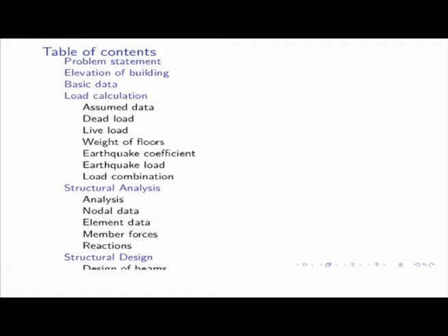So there are two aspects. One is that you try to handle it at the design level. Otherwise, when you have already considered all aspects of design and even then the lateral vibration is more, then you control it with a structural control mechanism. The tuned mass damper, tuned liquid column damper, so many things are available nowadays, and they do it on the basis of that.